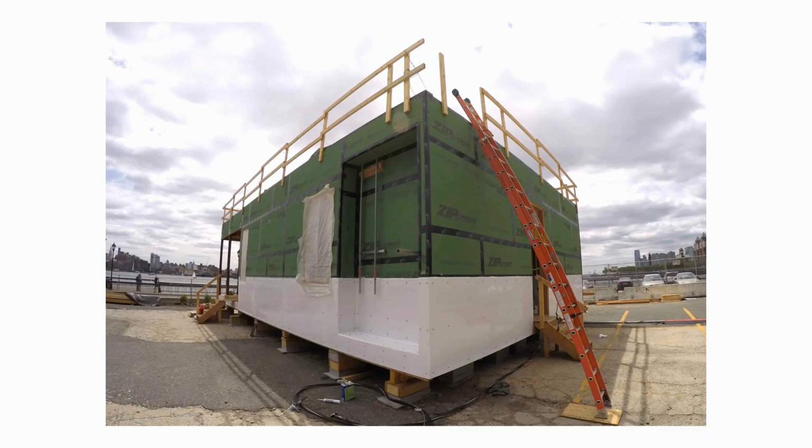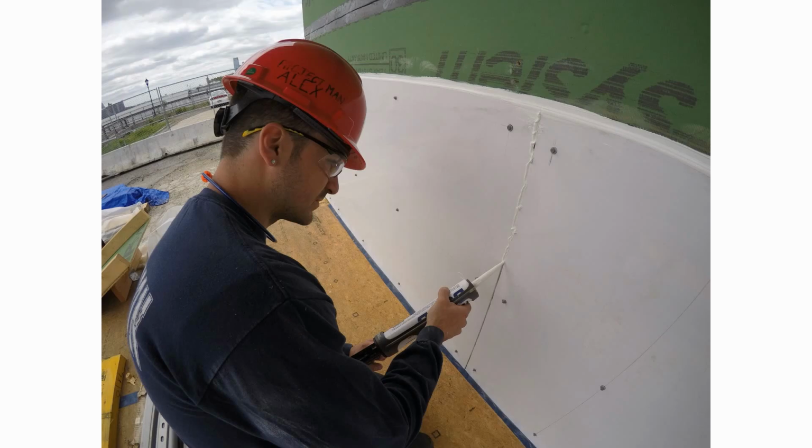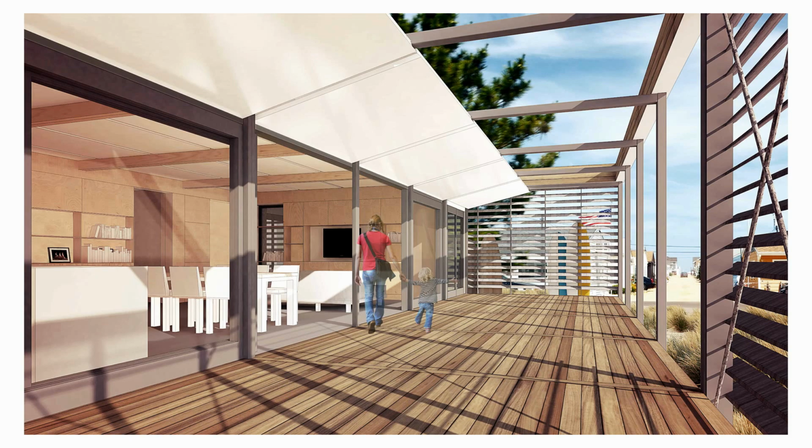And so that basically turned the floodproofing into a layer of well-designed plastic that was essentially boat grade sheathing. We used existing marine detailing, like for caulking and all the hardware that we use, the screws. So it was just basically using existing technologies but recycling them into a house. So the envelope then was just a stick frame reconfigured.